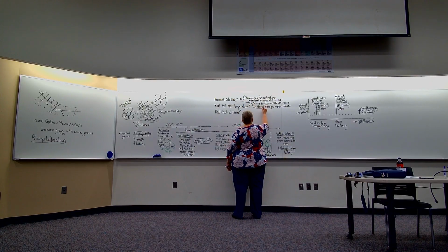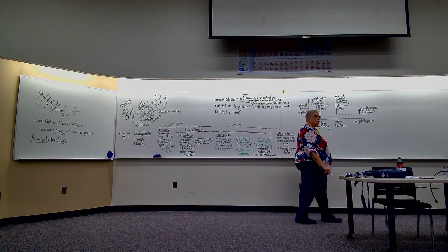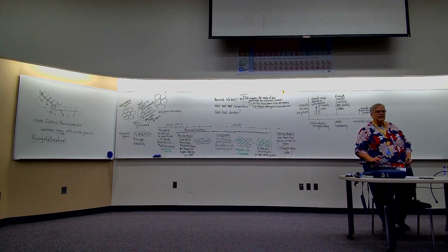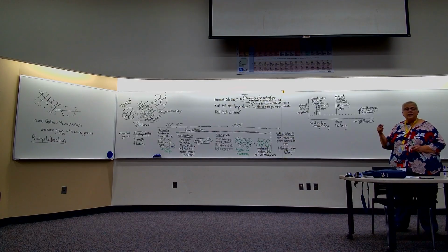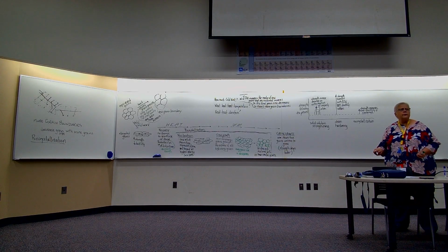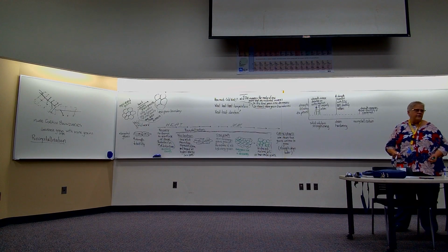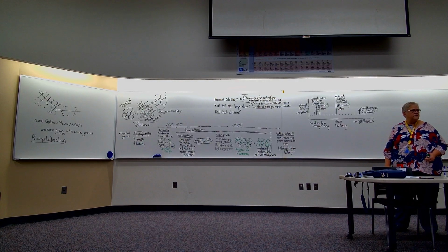Well, I'm going to try to figure out how much more I can add. How much more cold work can I get? I'll do that at the beginning, just knowing if I go more than 40% cold work, it starts to break. Okay, I'm not going to go more than that. Maybe I'll go 35. And I'll revisit that later.